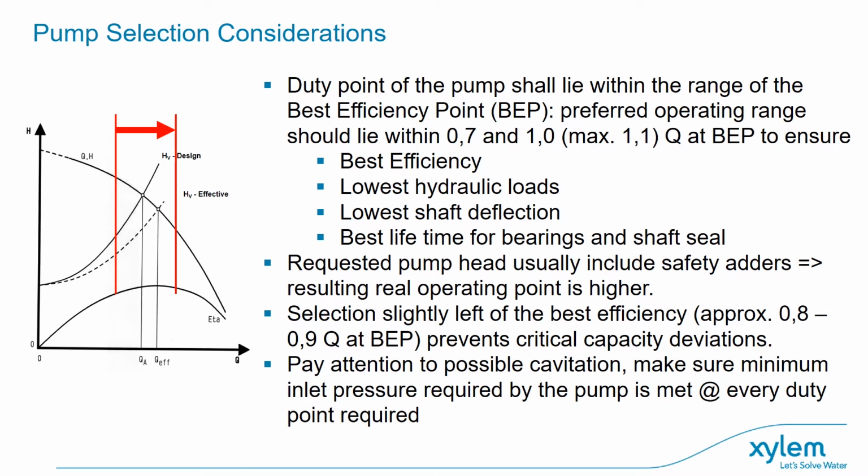We also need to take into account the suction conditions, to ensure that there is enough positive suction pressure to allow the pump to operate on its performance curve as it is designed. Again, with the wrong suction conditions, we can also increase cavitation, which will dramatically reduce the pump components' life plus the bearing life of the pump as well.